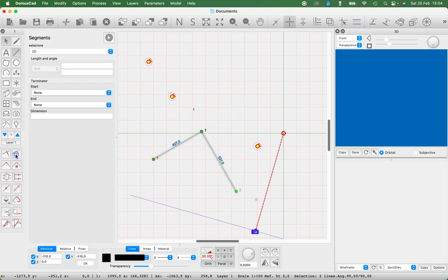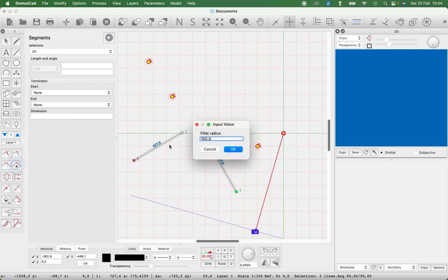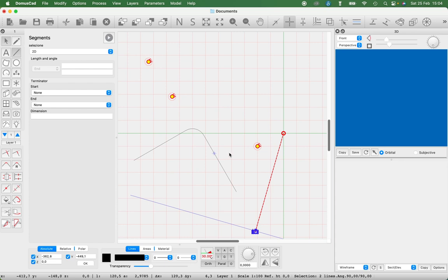Join, cut and delete the shortest strokes. Join, if necessary, cut at their intersection, two lines or two walls and delete the shortest ends. Circular fillets creates a circular connection between two lines or two walls. Circular fillets with radius creates a circular connection between two lines or two walls setting a radius.